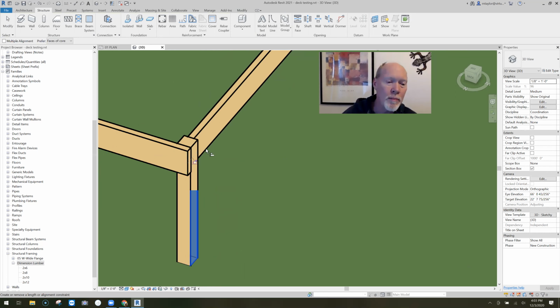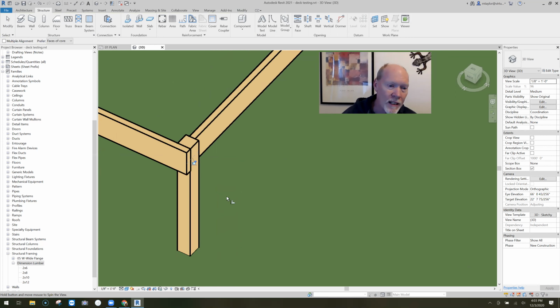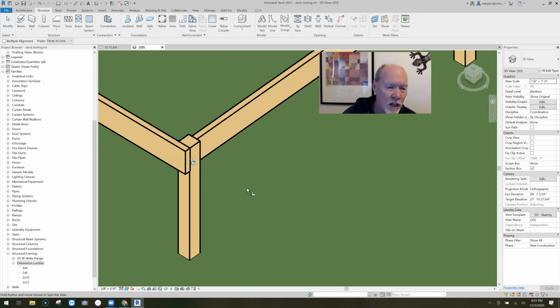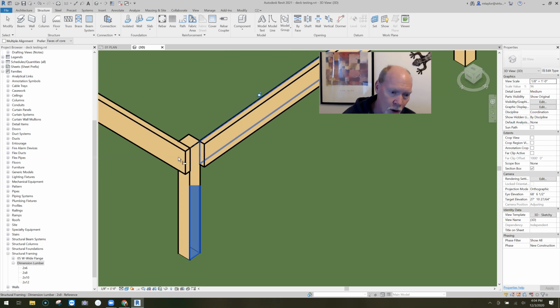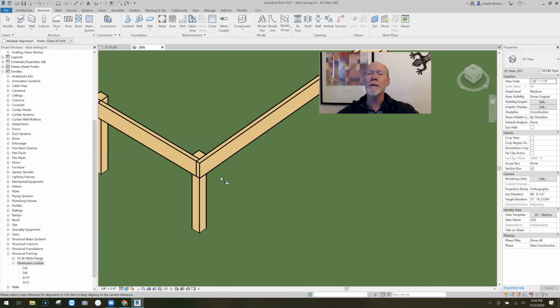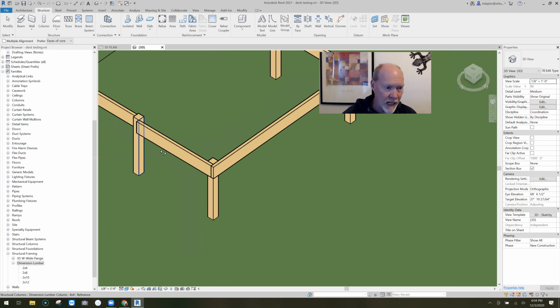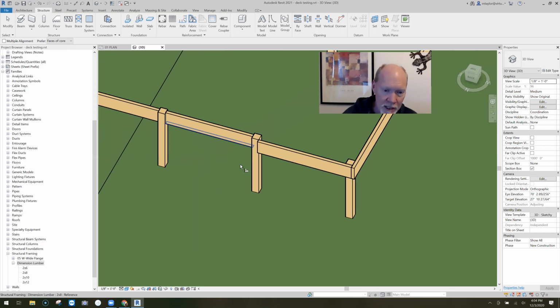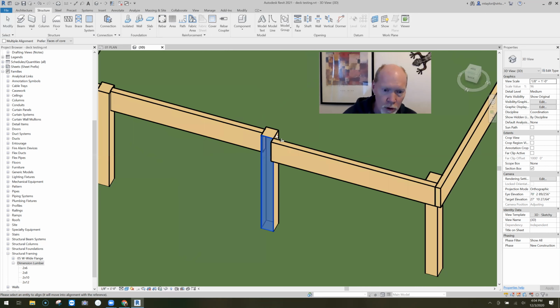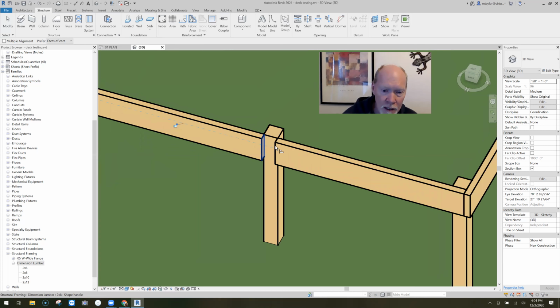So you can actually manipulate, let me just show you. See, manipulate where these beam ends go. So I'm gonna say, come to the face, back side, come all the way to the face of this beam, end. So do you see what I'm doing here? Because I used a beam tool, the structural members are exactly structural size perfectly, and I can make them align where I want to. So now, because I broke this, I'm gonna say come up to the face here, and maybe this end goes to that end.